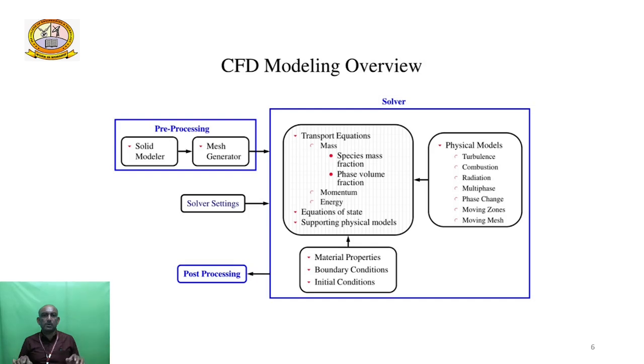After we plot the control volume domain, what is the inlet condition: the pressure, density, temperature. Then what is the outlet condition: pressure, temperature, density. These are the boundary conditions. We have to feed these known input boundary conditions to the solver equations. Then the system will analyze or iterate many times.